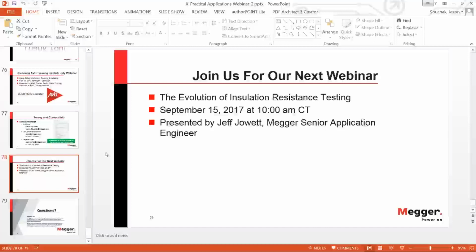And in the end, it all comes down to what Jason said at the end: what is your plan? Why do you do testing? If you do it because of cable replacement, then you're typically only interested in the aging condition. If you are really interested in making sure these circuits have high reliability, you have to do a global and a local test, a combination of both, which could be tan delta and partial discharge. That's probably the most common way to do it today.